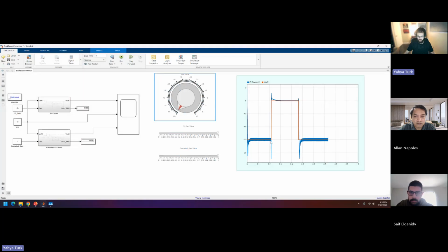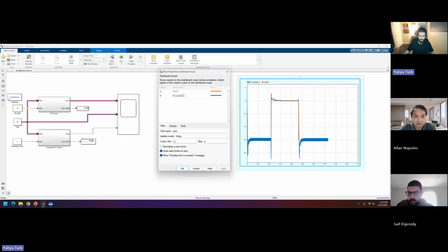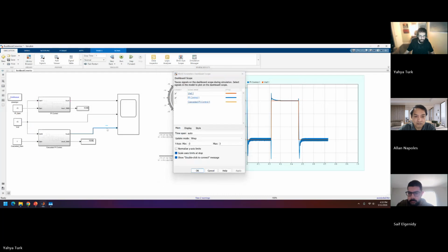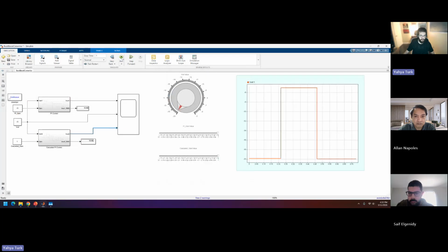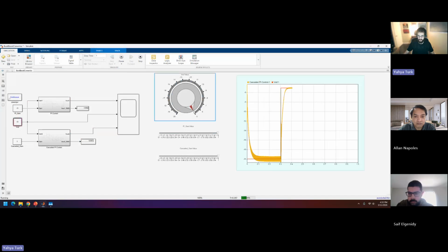And we see unfortunate voltage overshoots when transitioning from, I guess it would be low voltage to high voltage, but in our case, because it's inverted. And then we can do a simulation for the cascaded controller, which we see works a little bit better, especially at low load. So it doesn't have the overshoot, and you can have the transitions.